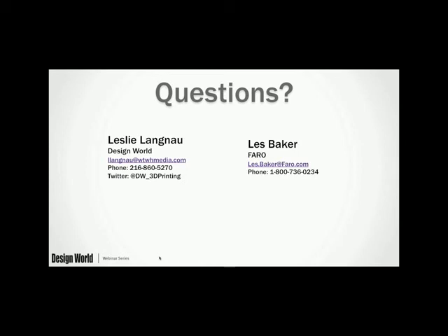The individual points that you measure will be very accurate, perhaps to within thousandths of an inch. But sometimes the points that you don't measure are as important as the ones that you do. So if you can capture a lot of points, particularly using the hard probe, then the geometry that you create is going to be very, very accurate, and you're also going to be able to investigate the form of that cylinder or circle, however you choose to measure it.